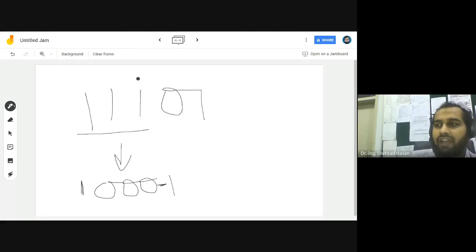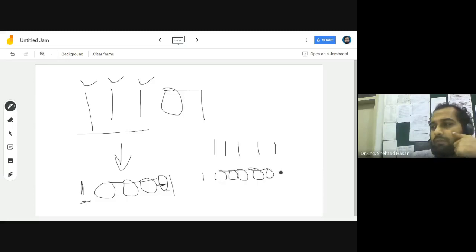Okay, so instead of having 3 additions, you will be doing 1 addition and 1 subtraction. So this makes the number of operations less than the previous case. This is only going to have benefits if you have got a sequence of ones. So if you have got in a number some ones like this, actually this number is 31, but you can convert it into 32 minus 1. So instead of having 5 additions, you are going to do just 1 addition and 1 subtraction, and then you're going to get your result.